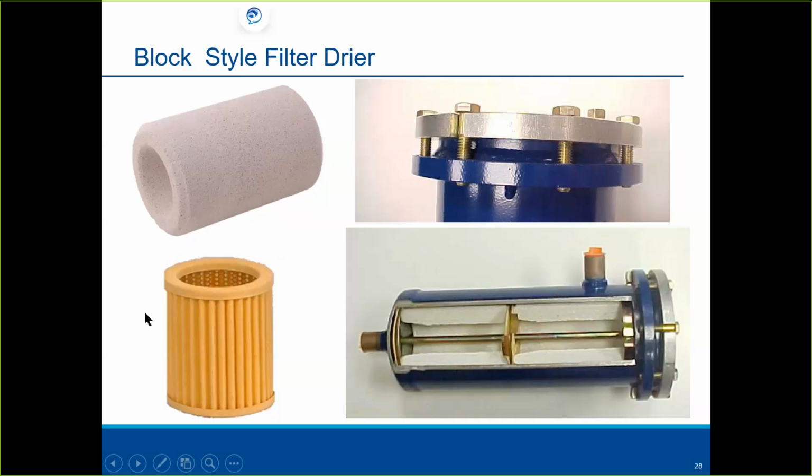This is the filter dryer that you would leave in permanently. This just picks up particles, all right? It doesn't cause near as bad a pressure drop as a block does. This just shows the cutaway, all right? Obviously, this is the type that would be in residential. If you're in the residential world, you'd want to have some kind of ball stop on each side of this to do preventive maintenance, okay?